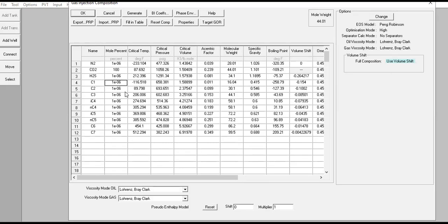The default setting for very small or zero is like this. And for CO2, of course, the mole percentage is 100%. If you want to use MBAL for CO2 storage, you must use this setting. If you inject pure CO2, it will be 100%, and you maintain the format of the table. You cannot paste only CO2 for one row. MBAL will reject it. So you must copy the table, paste it on this table, and then change the percentage for the other components. For CO2, it will be 100% if it is pure CO2 that you inject.